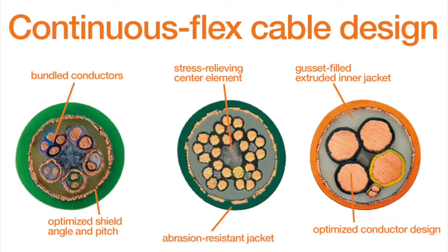And when we're looking at the strands, there's some cables that use a thinner strand of copper, where other cables use a thicker strand or even solid copper for the conductors. With continuous flexing cables, we want to use that medium grade to medium fine level, because we want to make sure it's thin enough that it's flexible and able to be moved in a continuous flexing cable carrier application where it's not breaking.